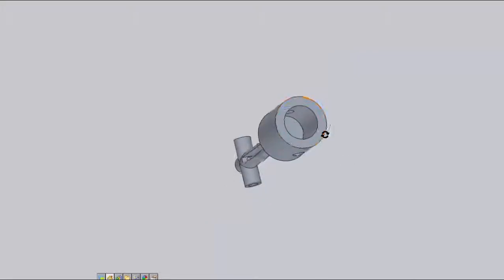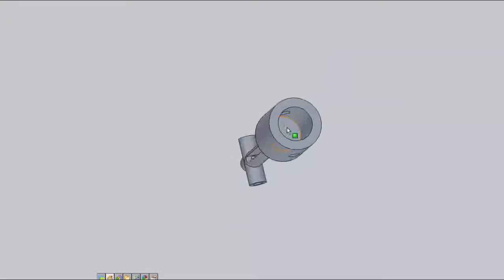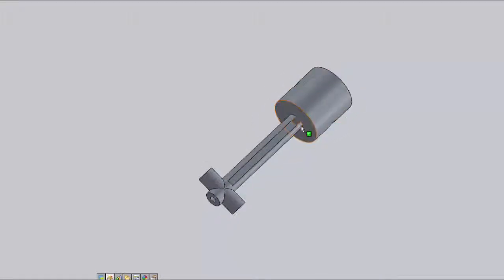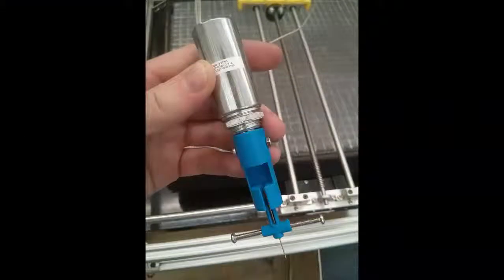In a separate copy, I ended up having to make this hole larger with a Dremel tool to fit the solenoid plunger because these holes were too low. This melted through the plastic here, and the end just snapped off. The actual model we used in the final design included a thicker amount of plastic here and a much wider extended frame for the probe connector. And here you can see the final probe connector attached to the solenoid.